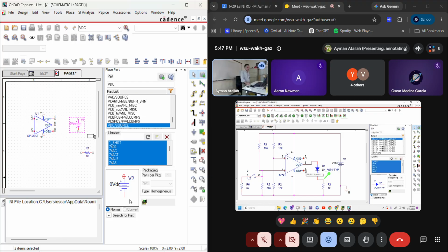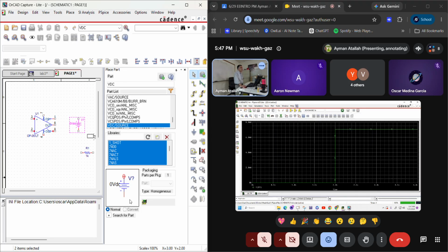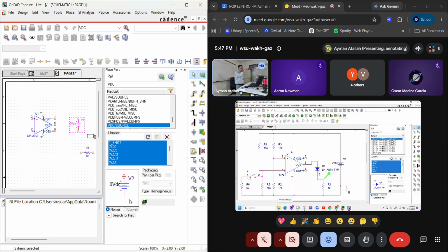So everybody is able to get this chart here. Like no voltage, then there is a voltage, or there is current, and then no current. Yes. Okay. So let me ask you an important question. This light emitting diode now will light for a certain time and not light for other time. Where does it get the power? Who delivers the power to the light emitting diode from this circuit here? Transistor? No transistor, we don't have transistor. You mean operational amplifier? Oh, yeah. Yeah, the op amp. The output of this device is powering the light emitting diode.